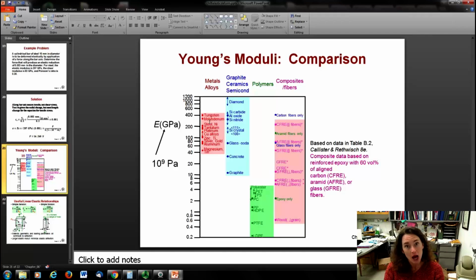If you take a rock and you try to stretch it out and draw it into a wire, you start stretching it, it'll just break, okay? So there's a big difference between an elastic modulus and how resistant something is to fracture. These ceramics are very resistant to a small pull, and if you pull them too hard, they just fracture and break.